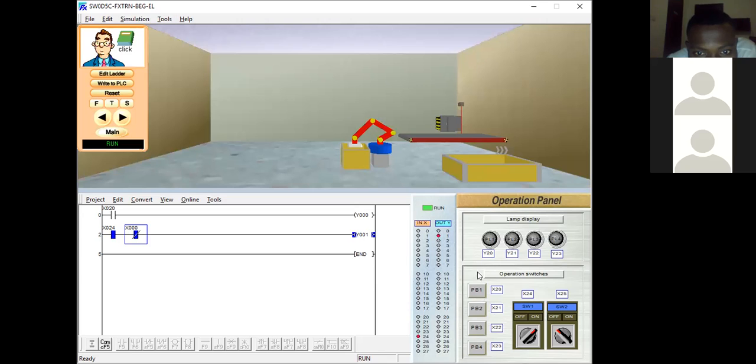Great. Now let me supply product. Product is supplied. Notice something. Immediately the product gets to this sensor, the sensor stops the conveyor because it has now opened this contact. So this conveyor is no longer getting power. For this conveyor to continue to get power, whether I turn it on and off, nothing changes. I need something to reset that sensor.